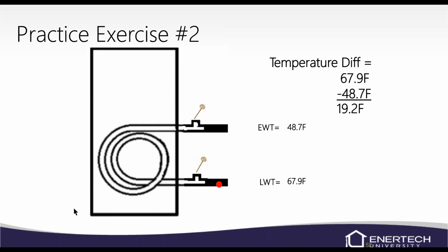In this example, if you have a flow center with pumps, you may see this and go, well, I may not be moving enough, so we need to check that pressure drop. Because normally, again, it's going to be about 8 degrees on a closed loop, about 16 degrees on an open loop, depending on flow rates. So you'll look at this and kind of see.